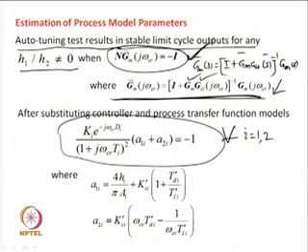So, we will get two analytical expressions basically, but in general form, upon substitution of the various G's, GM and GCL, I get an expression of this form, where A1 I is equal to 4 H I upon pi A I plus K C I dash times 1 plus T D I dash upon T I dash, and A2 I is equal to K C I dash times omega CR T D I dash minus 1 upon omega CR T I dash.